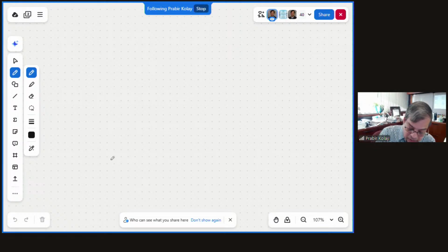So first thing is problem number 5. You need to calculate the degree of consolidation U equal to 90%. You can calculate the time factor T_V from the table, or you can use the equations. If it is less than 60%, T_V is pi by 4 times (U by 100) whole square.